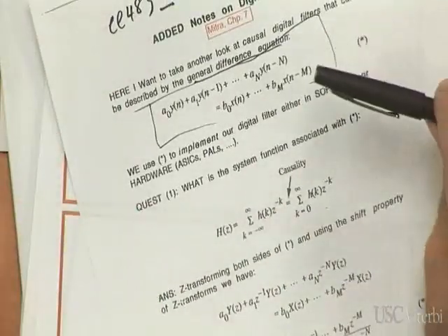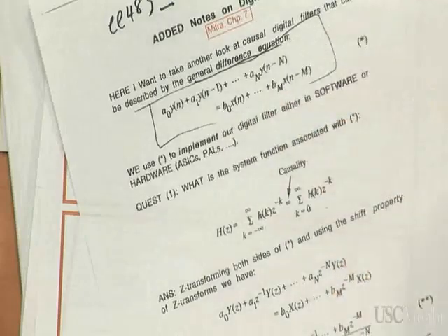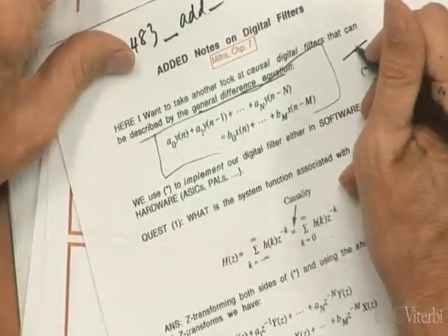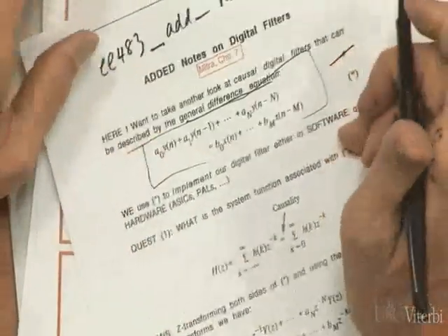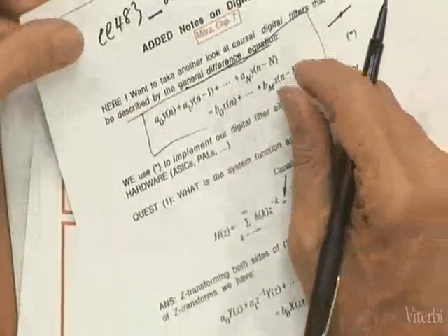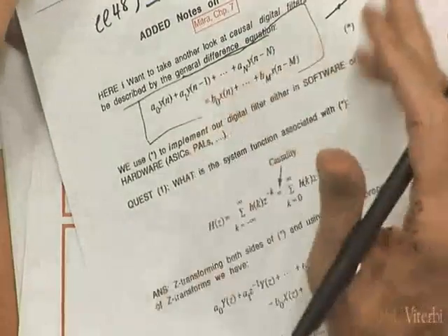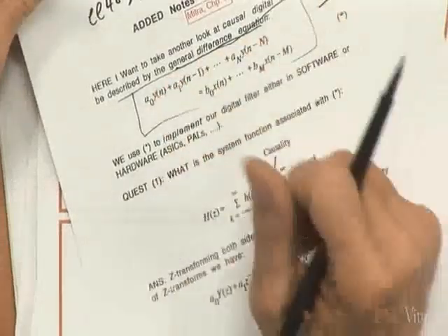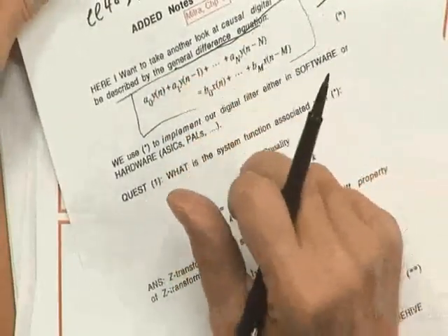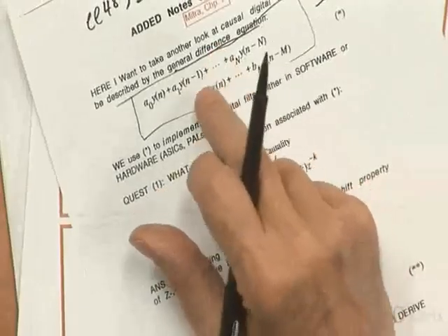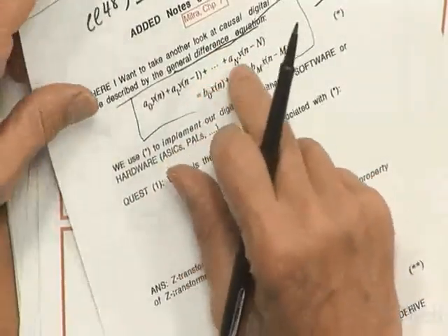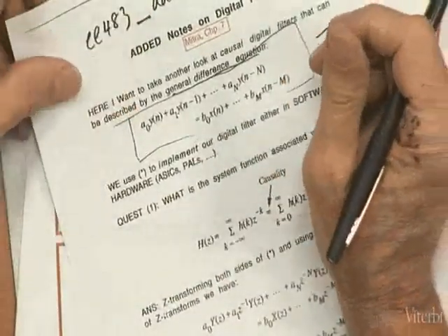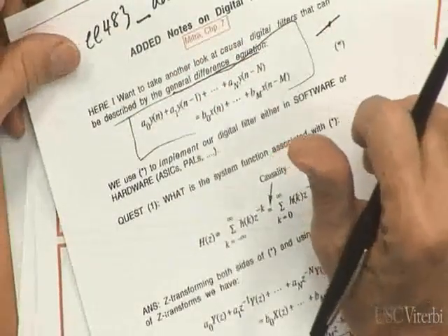Now I should tell you, when you want to build one of these digital filters with an FPGA or an ASIC, or in software, this is what you use. This is what you use, the time domain representation. You generate this using the FPGA that multiplies or adds. You do have to register certain values because there are delays, and then there are also multiplies. Typically, for a pipeline, you register the values after the multiplies, etc. But this is what you use to implement the digital filter. You use the time domain representation of the difference equation.